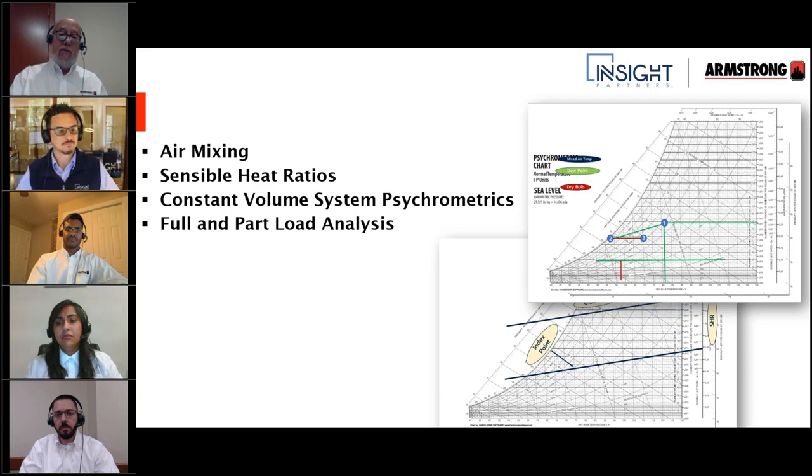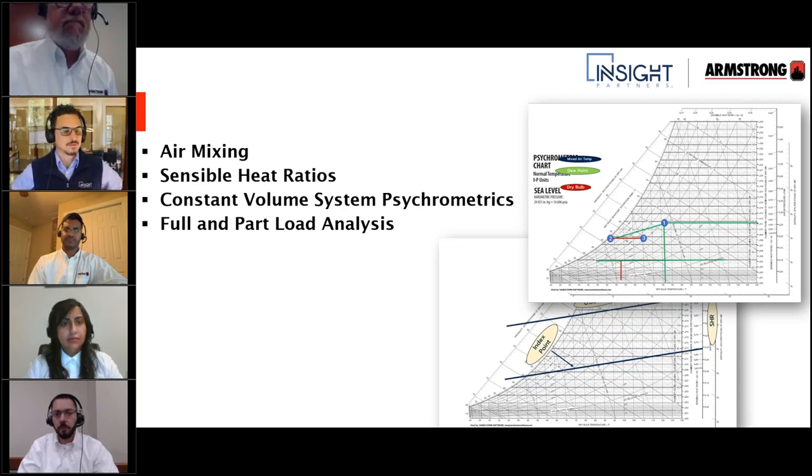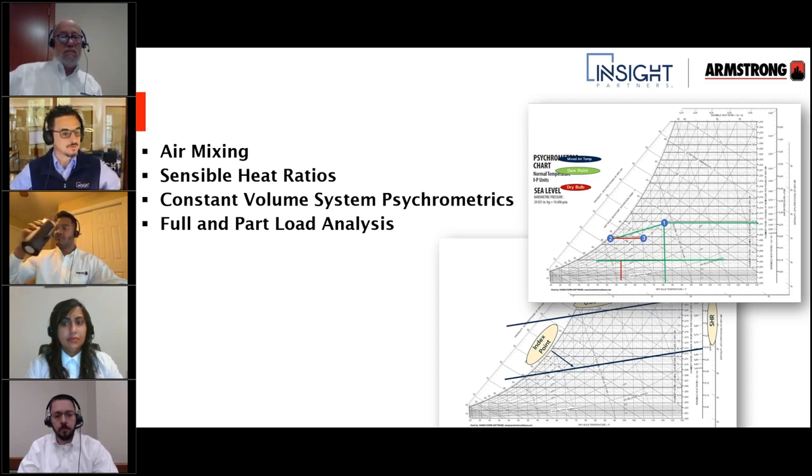Like I said, there's a stoichiometric chart, which is for flue gases, and it looks drastically different than a psych chart, but it's all the same information. It's just in a much different temperature range. And because the mix of air is different, it doesn't have the same properties, because there's other gases inside there other than just breathable air. So it behaves differently, and it has different moisture properties and all that goes with it. The biggest difference I've seen is whether it displays grains per pound of dry air or pounds of water per pound of dry air. That depends on which units you prefer. Some of them don't have dew point on there. You just use the wet bulb saturated point as dew point. We kind of looked at it a little bit earlier, but yeah.